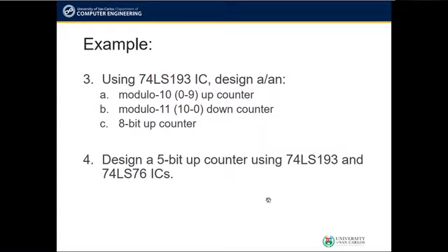In the next examples, we shall be designing counters using the 74LS193 according to these specifications. For the first one, let's try to design a modulo 10 up counter that counts from 0 to 9 and then repeats. Let's go straight away to Proteus and show the circuit. The circuit looks like this.